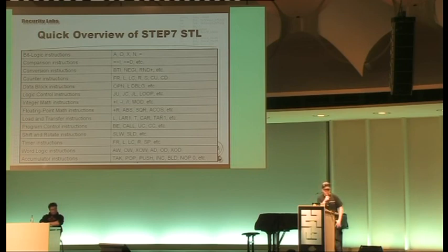The PLC, from the MC7 bytecode level, is not a von Neumann architecture. From the programming point of view, it feels more like a Harvard architecture. So you cannot mix code and data easily. What you actually do is you have different types of data blocks, and of course, instructions to deal with them.